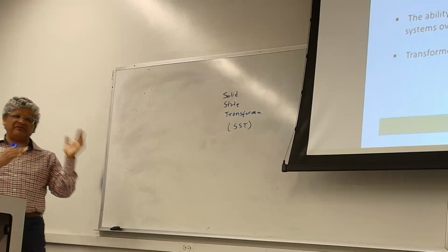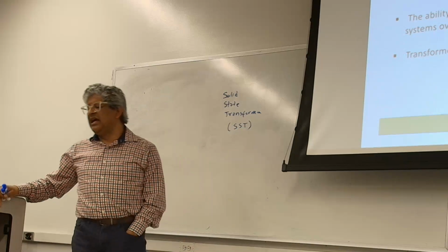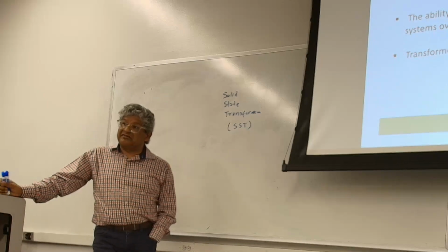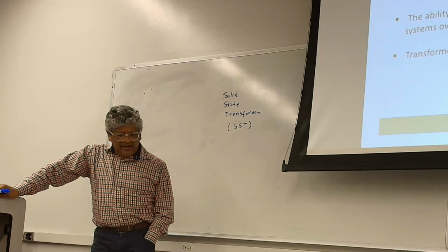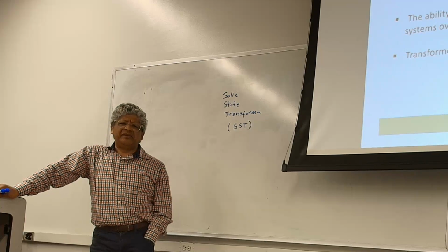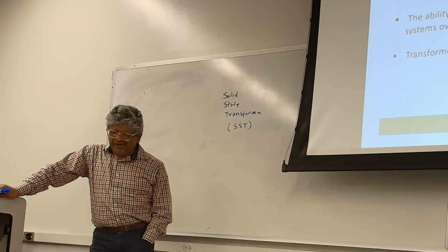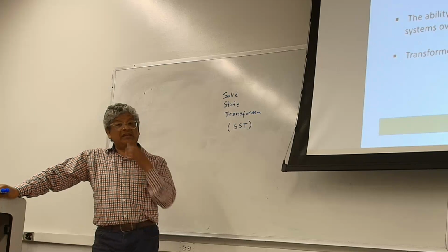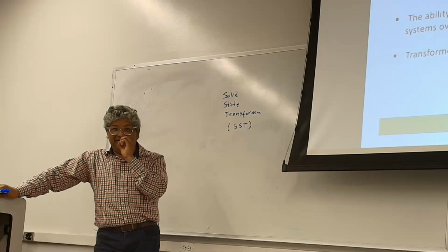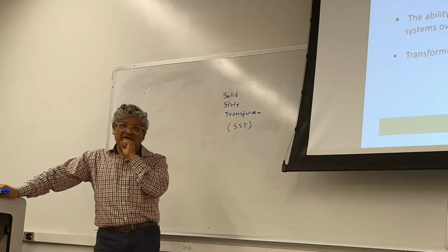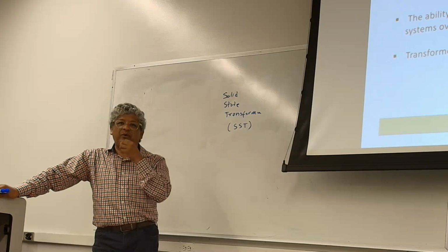And there's a whole bunch of different flavors that these things come in. It's not a new concept. As I said, there's a company called ABB. ABB actually came up with this solid state transformer back in the, I want to say, mid 2000s. And the challenge is that they're very expensive, and the key thing, they're not as efficient, because you incur a lot of losses in the power electronics, right?